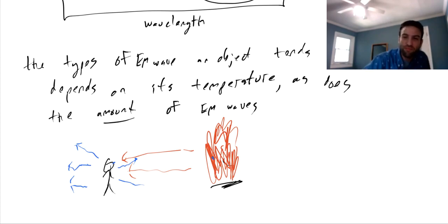Okay. This is one of the ways that, if you're standing in front of a fire, you can tell that thermal radiation is really important, and even more important than convective heating. If you're in front of a fire and you put your hand in front of your face, the portion of your face that's shaded will suddenly feel a lot cooler. And that's because the actual air in between you and the fire doesn't warm up by as much as maybe you think it does. The direct radiation of the fire hitting you is really what's creating a lot of that sensation of warmth on your face.